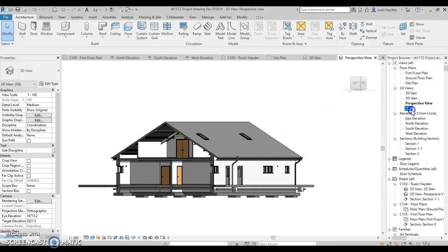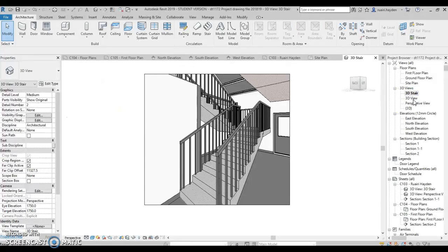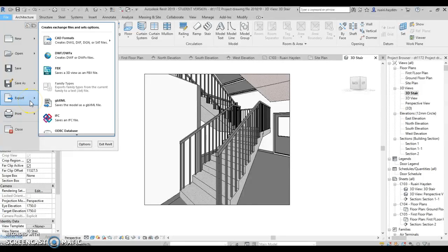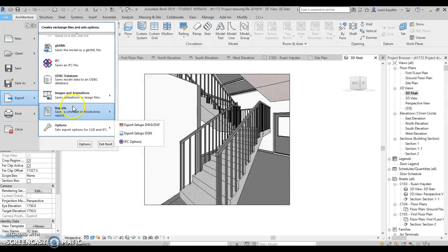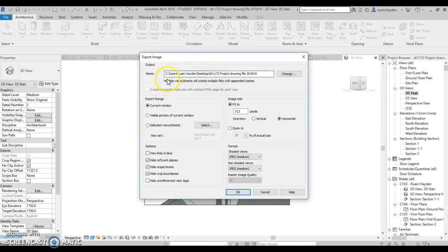I hope it's of some help, and what it allows you to do, though, it allows you to use in presentation. So again, the last thing then that I want to do is to export these views. So if I go clicking over here and export this view, I can export, go down here and click as an image, and I'll go image, current view, and OK,